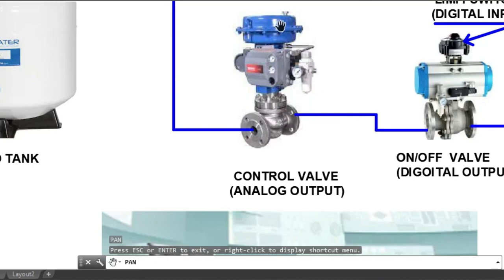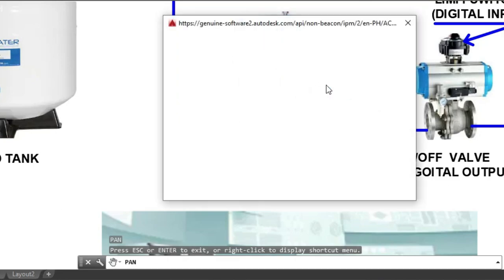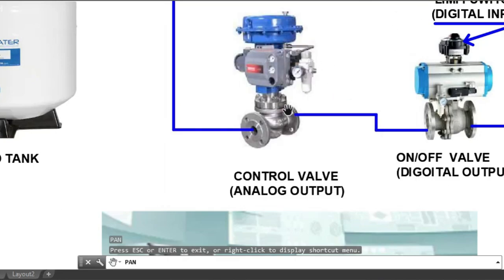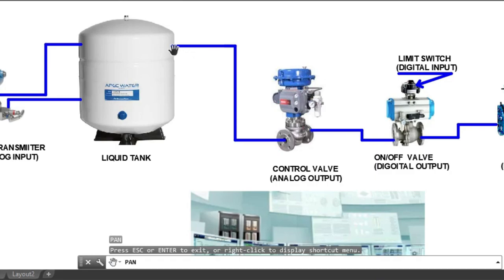The operation of this control valve is variable opening. The DCS can send an analog output signal to open this valve variably. Like the DCS can send 25% open to this valve through the I2P, through the positioner. The DCS can open a variable like 20%, 50%, 25%, and 100% opening of this line. This is the process line going to the tank.